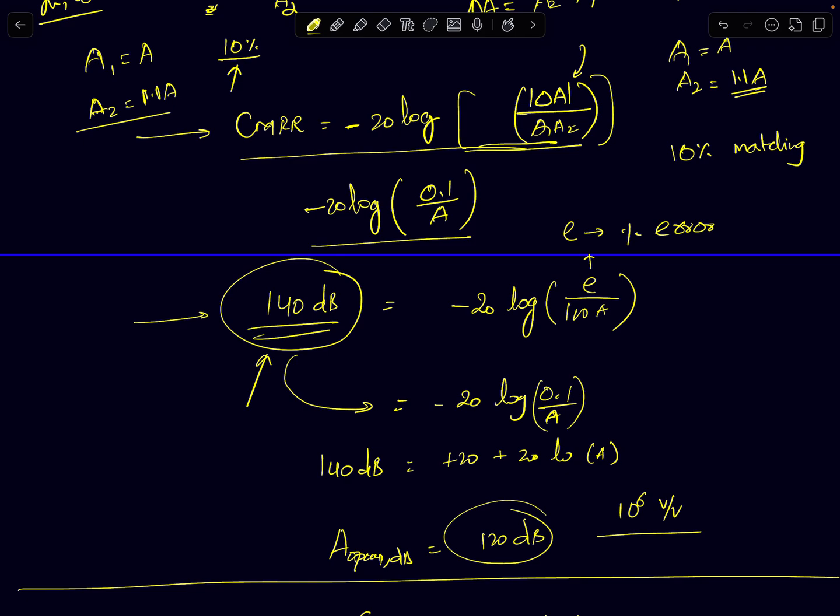When you want to achieve high CMRR, let's say you have matched all your resistors very accurately. Even then, you may end up having some finite CMRR because the op-amp gains are not matched. So you will have to ensure that for the op-amps to have good matching, the DC gain itself can be higher. Here I'm assuming that the DC gain and the percentage error are not correlated, meaning I can have a fixed percentage error for higher gains as well. Which is not a bad assumption. So that's something to keep in mind.